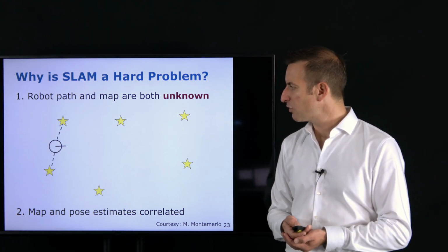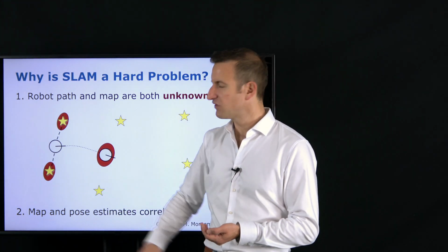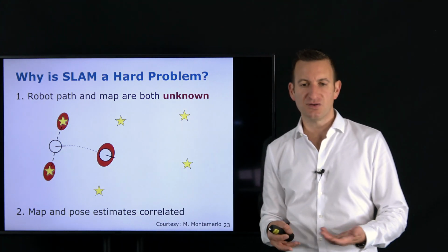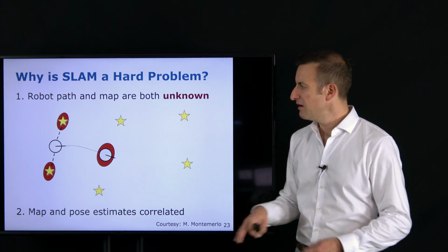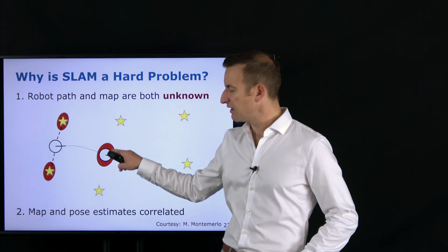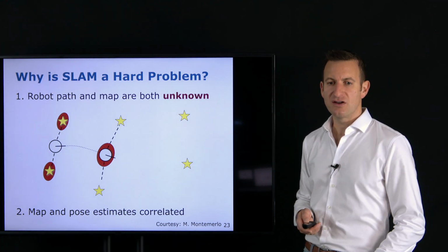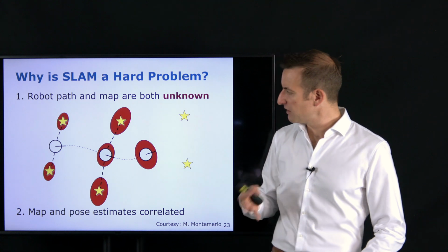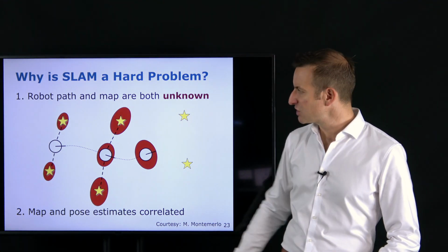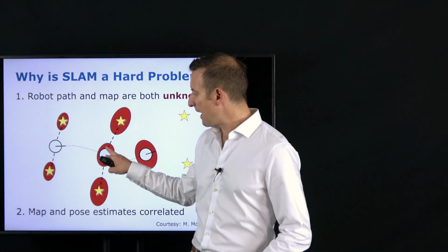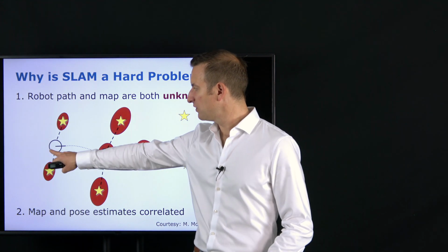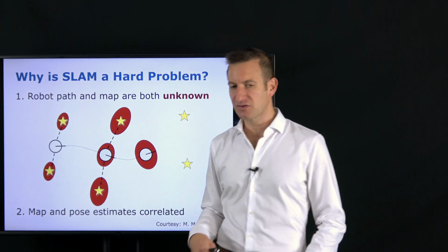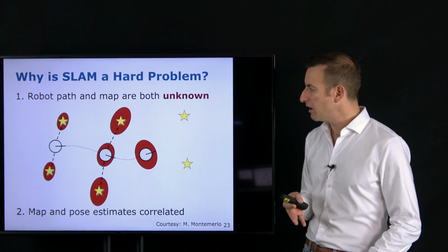You start with the robot moving around, it sees those landmarks in the environment, and the circles represent the uncertainties that we have. Then the platform moves through the environment and its uncertainty actually increases. It observes new landmarks. Then, of course, the uncertainty of those landmarks, at least in a global frame, is larger than those over here, because the system had a larger pose uncertainty than the initial uncertainty, and as a result, the positions of those landmarks in the robot system are more unknown.